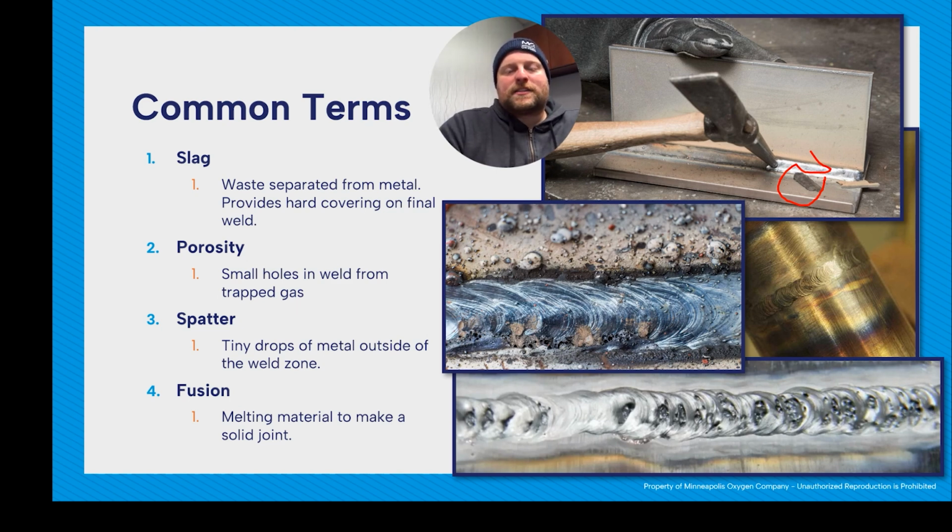Porosity, that's small holes in the weld from trapped gas. This bottom picture here is just chock full of porosity. That's going to be from inadequate shielding, allowing that atmosphere to get in. Contamination on your actual base metal will do it, like oils, water, anything organic can help create that porosity. Bad, don't want it.